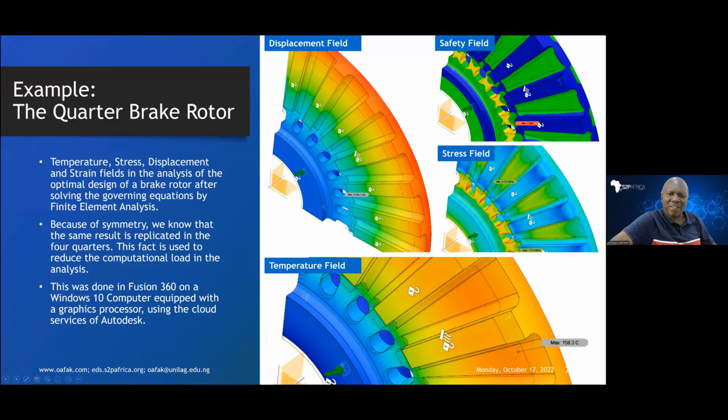A stress field is where a tensor value of stress is available from point to point. For instance, you can see that even though the temperature at the point where you add the bolts, where you have these openings, is very low, the stresses are very high there. So the fact that you have low temperatures, which is shown in blue, doesn't mean the stresses will be low. The temperature field is completely different from the stress field, even though what is causing them is the same.